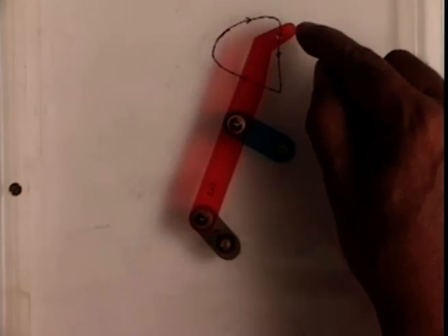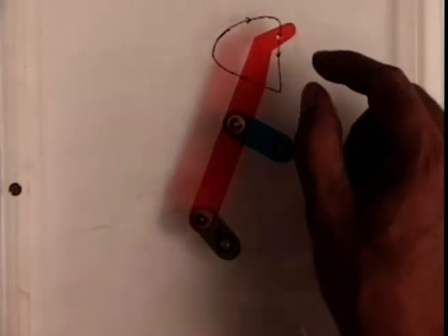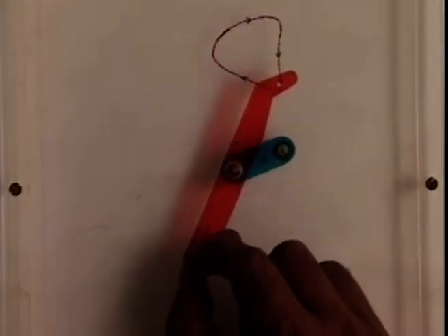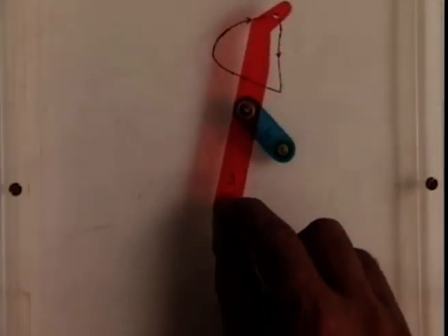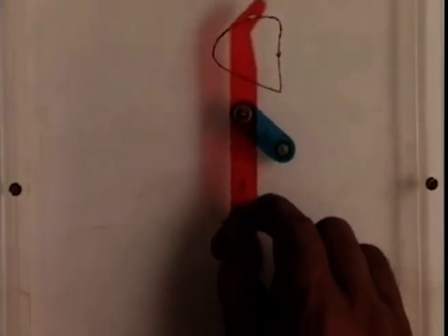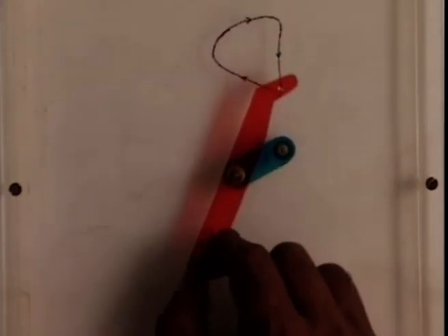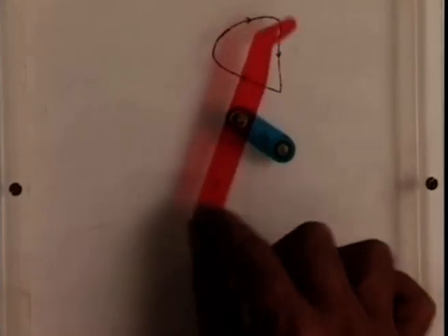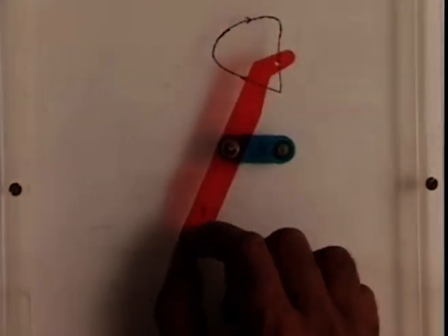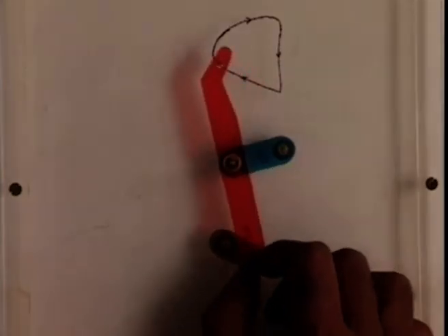Now this end of this coupler can be used as a hook which gets into the sprockets of the film and drives the film downward. Here it comes out of the sprocket, goes out and again gets into another groove, another sprocket, and draws the film downward. So this way it can be used for driving a movie film in a movie projector. If it goes very fast, the film also moves very fast. The critical thing is that it must move almost vertically here to drag the film downward, and then gets out of the film and again gets into the film and drags it downward.